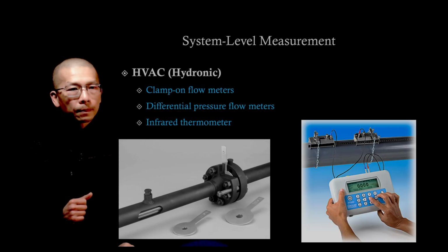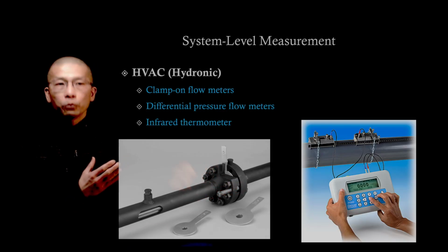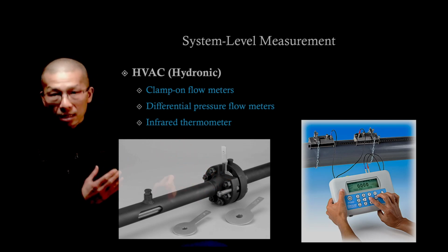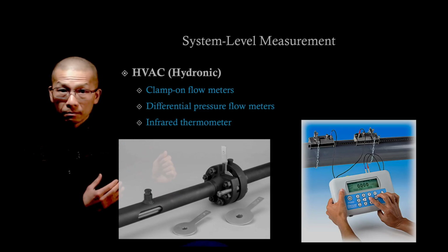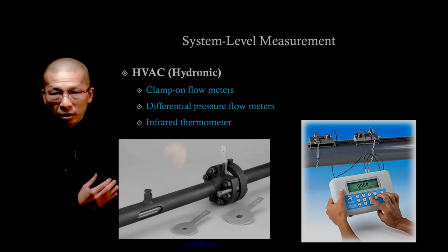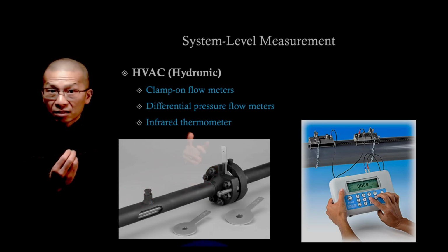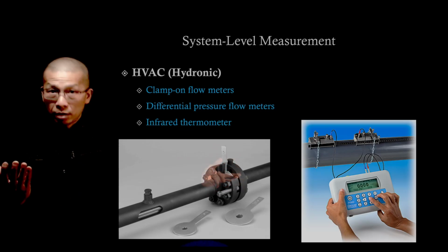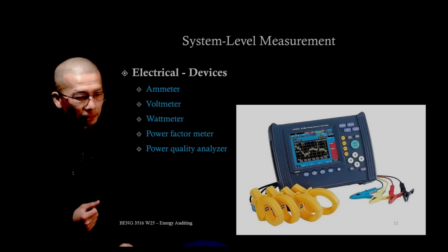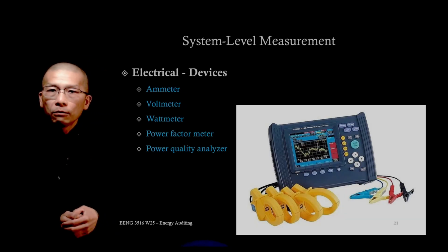Okay. And again, if there's any short circuit, we can detect that as well. If there's a very low delta T, then something is not right. If you use your infrared thermometer and find a return pipe almost as hot as the supply, something is not right.